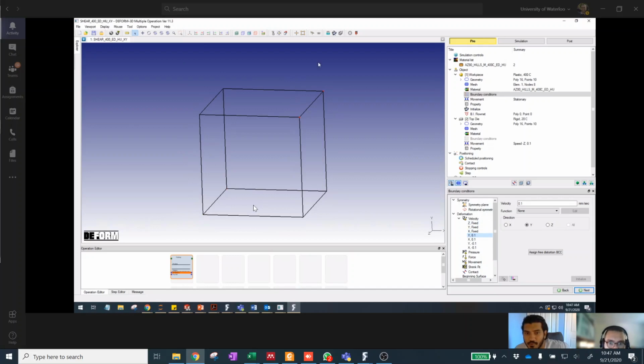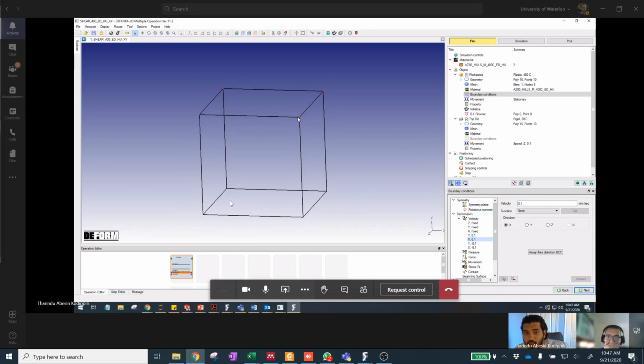So this one pulls up in the Y direction, these 2 points. And these 4 points pull in the positive X direction. I think the problem is you're applying those simultaneously. This is one boundary condition where you're pulling in the X, but you're not pulling in the Y. Simple shear, I'll give you a diagram here, maybe I can post it to the chat. Simple shear is these fixed in the Y direction. Those 4 points are fixed in the Y direction, and you're only pulling in the X. That's what you have, I think.